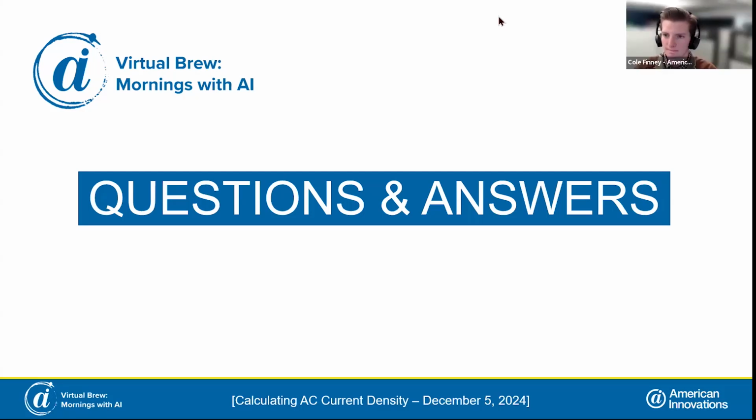Yeah. Oh, go ahead, Mike. Hi, Jerry. I'm Cole, product manager for Triton and Bullhorn and everything. I'm just hopping in here. Yeah, what Ryan said is correct, because when you flip the switch, you're removing any DC interference on the AC coupon. So that would be why the AC coupon is not directly attached to that switch. That's just removing any DC interference from the test coupon that we have on the Triton. So since you have the native, the test, and the AC coupon, it'll be removing interference from the test DC coupon.